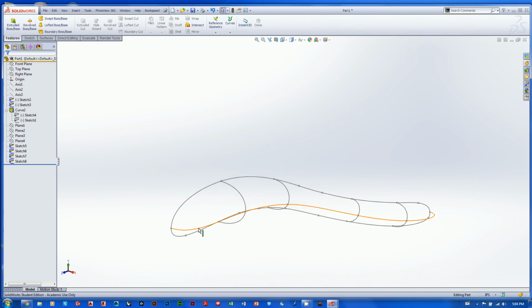We used our 3D sketch in combination with our center line and using the reference geometry, additional planes, to create planes, and then using the pierce command to draw sketches on those planes and piercing sketches to the line work we've created so far. So I don't want to get too far ahead of ourselves.